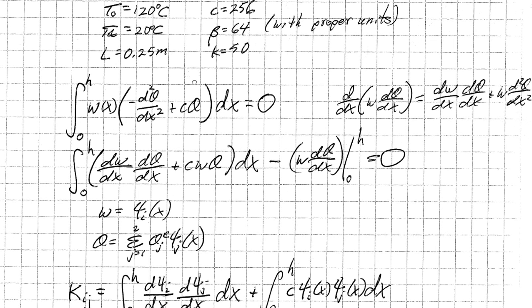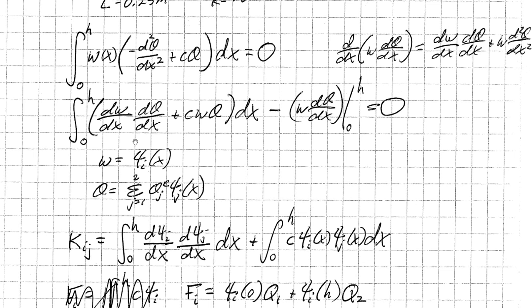Alright, so again, you're seeing us go from a strong form equation in this integral, we multiply times a weight function, we simplify this down into the final weak form of the equation. Here again, apply your product rule, you manipulate this equation and substitute it in for this term. What that gives you is a weakly distributed derivative over your weight function, your dependent variable, and a set of boundary conditions.